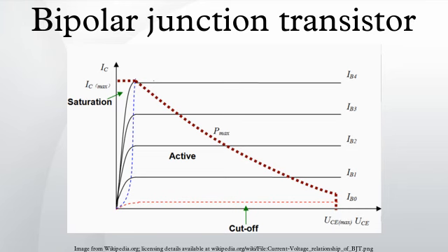Most of the current is carried by electrons moving from emitter to collector as minority carriers in the p-type base region. To allow for greater current and faster operation, most bipolar transistors used today are NPN because electron mobility is higher than hole mobility. A mnemonic device for the NPN transistor symbol is "not pointing in," based on the arrows in the symbol and the letters in the name.